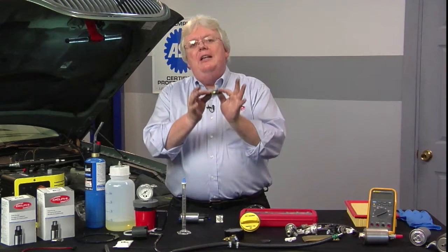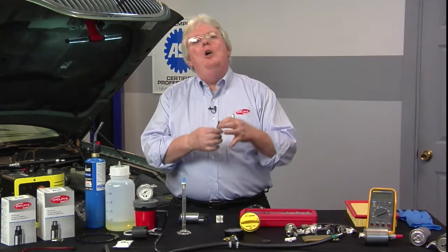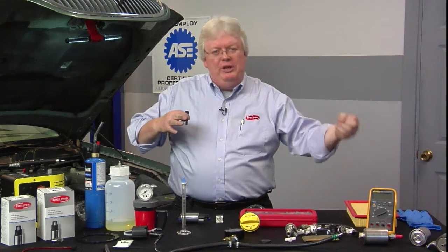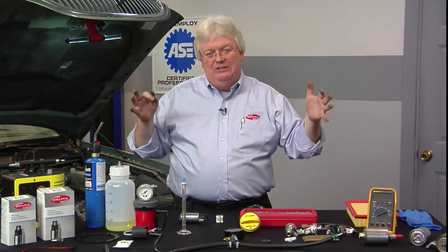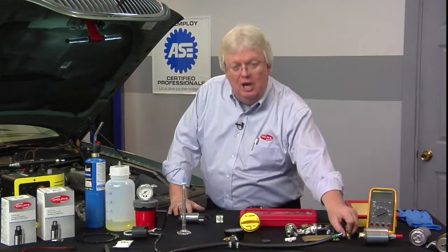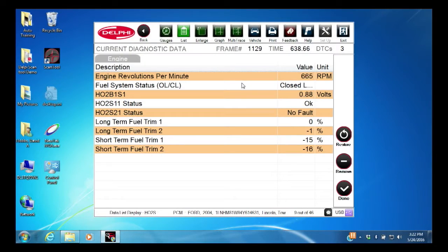Other sensors, the coolant sensor, intake air, could be saying it's much colder than it is without being a complete dead space of low voltage or extremely high voltage, what we call the dead zones, setting the code. It could just be skewed. So those could all cause a rich mixture that could result in what we're seeing here, some negative fuel trim numbers. Now what we want to do is to pull a vacuum leak and see if the O2 sensors respond.